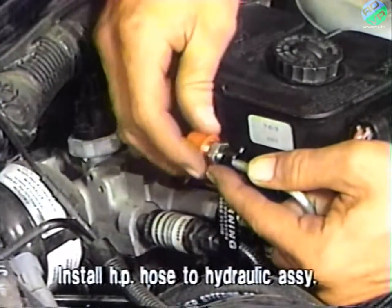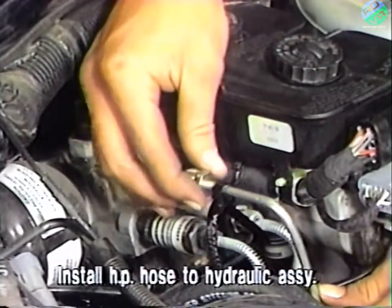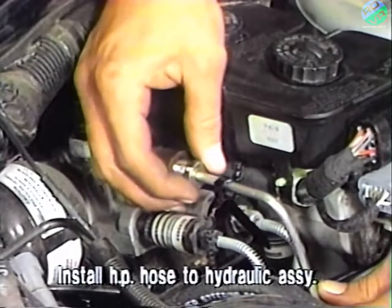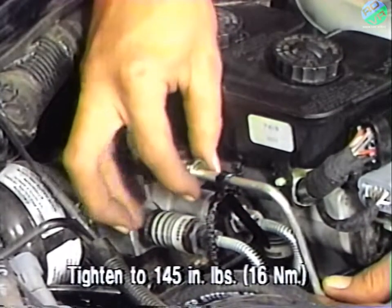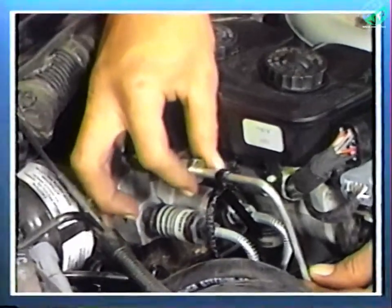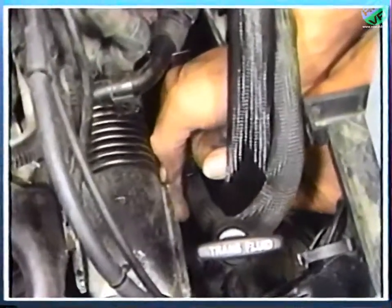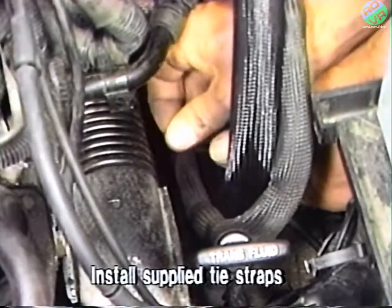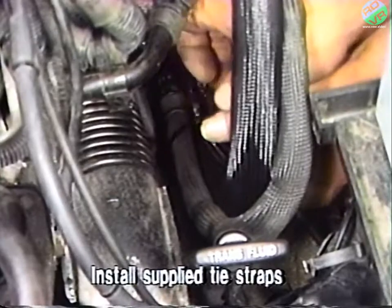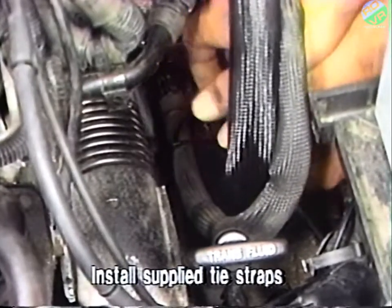Remove the cap from the fitting on the supplied high-pressure hose and install the end of the hose to the hydraulic assembly. Tighten the fitting to 145 inch-pounds or 16 Newton-meters torque. The following steps apply to all vehicles. Begin by installing the supplied tie straps around the hoses and wiring harness at the locations shown in the illustrations in the dealer recall notification letter number 526.